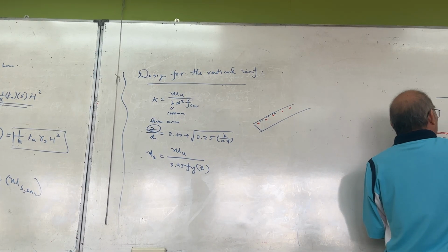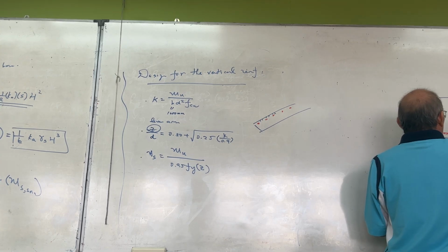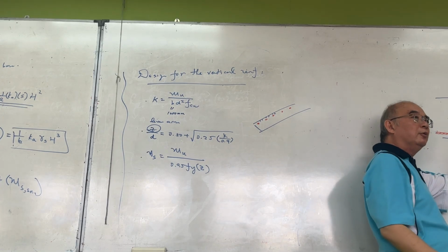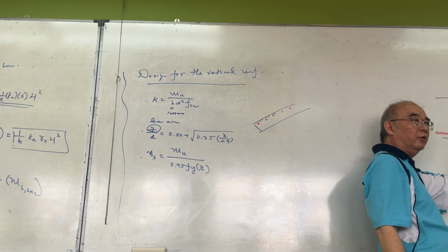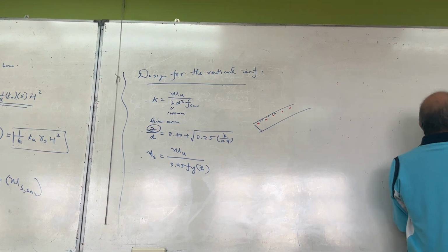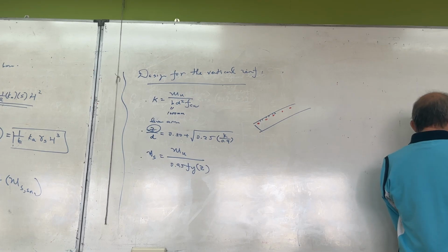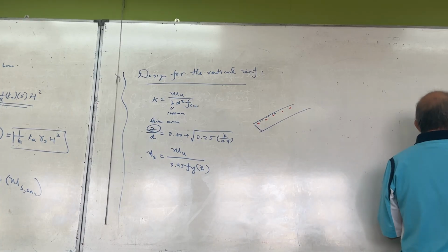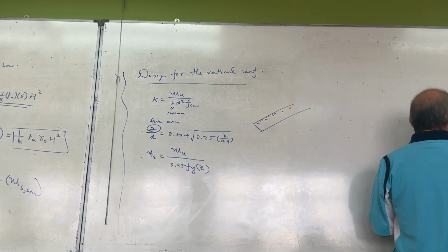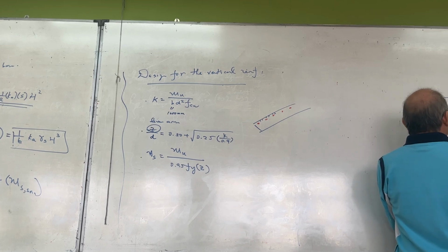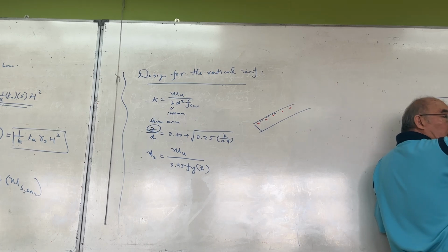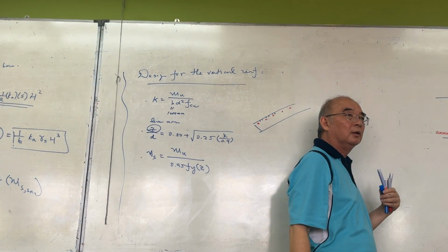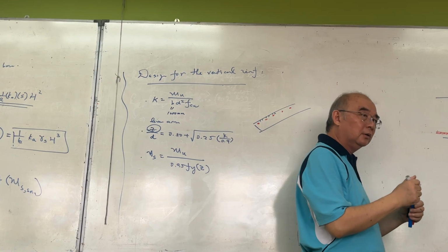So the rebar, the concrete actually has a distributed pressure, distributed stress on the concrete. Okay? So this is the tension. And here, this is T, right? And then, because this is a distributed stress, so this is the compression resultant. Okay? Compression resultant. Understand? No?